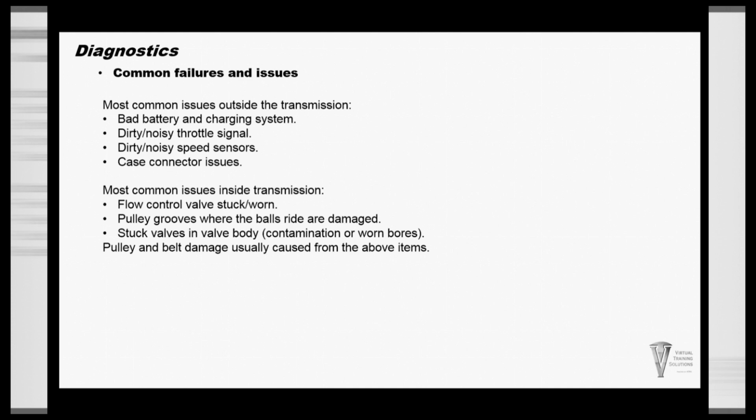Go ahead and repair that bore however you're going to want to repair it, and make sure you address that issue. Need to make sure you pull all the pulleys apart. There are balls inside the pulley grooves, and these balls like to break up and damage the grooves, and the balls will stop the pulleys from opening and closing smoothly. So you want to inspect the insides of the pulleys. Very, very big problem here.